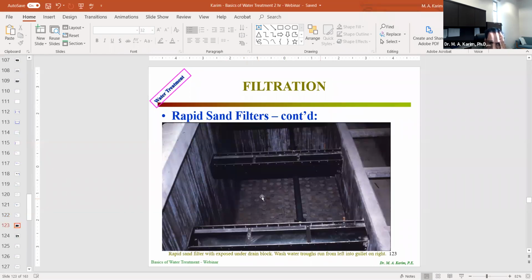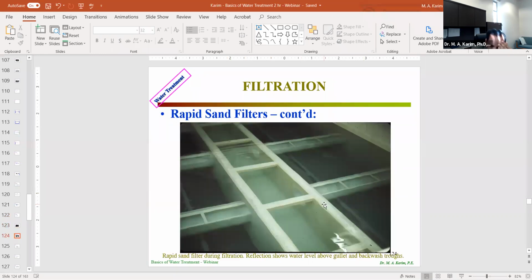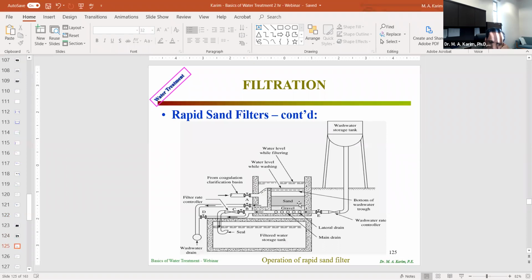So here is the sedimentation tank. These are trapped. There could be something in the bottom, put in, like say, sand and the anthracite here. So here is the other one. Looks like this is full of water. It's passing through, I mean, it's filtering. But the top layer looks very clean. So here is the backwash for that. Fraction of efficient filter, backwashing. So how can I backwash?